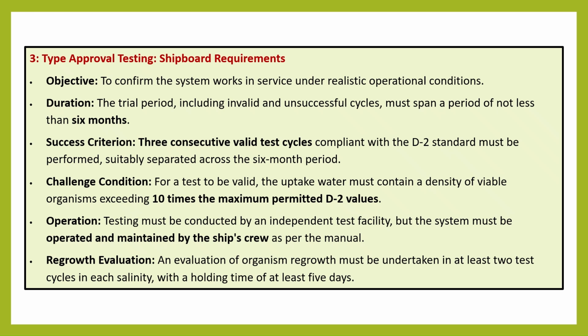Operation: testing must be conducted by an independent test facility, but the system must be operated and maintained by the ship's crew as per the manual. Regrowth evaluation: an evaluation of organism regrowth must be undertaken in at least 2 test cycles in each salinity, with a holding time of at least 5 days.